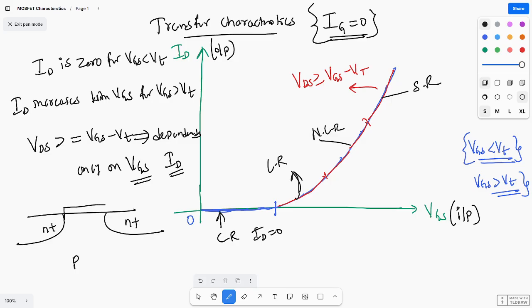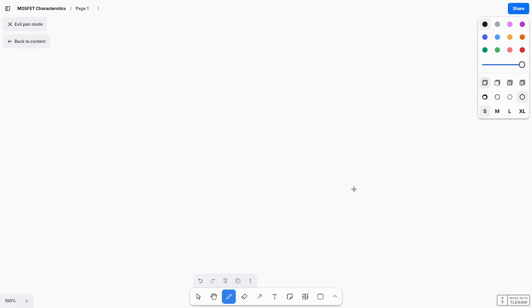Here I am connecting with the SiO2 layer, silicon dioxide. This is nothing but an insulator. Above this there is polysilicon or metal, and here you are giving the gate. So due to this insulator, the gate current is 0. If gate current is 0, there are no input characteristics. Which characteristics are there? Transfer characteristics. So this is about the characteristics of enhancement NMOS.